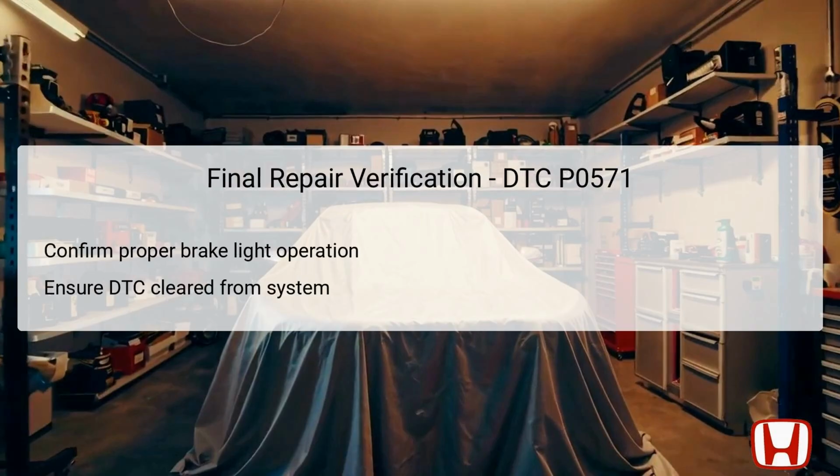After completing all the necessary repairs related to DTC P0571, it is crucial to verify that the repairs were successful before the vehicle leaves the shop. Starting with confirming that the brake lights operate correctly under all conditions is essential. Once satisfied, it is important to recheck the vehicle's onboard diagnostic system to ensure that the code DTC P0571 has been successfully cleared.